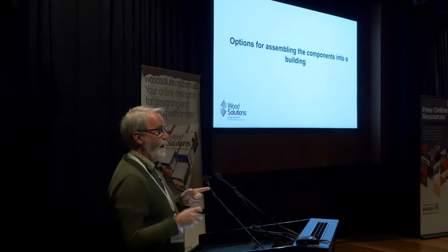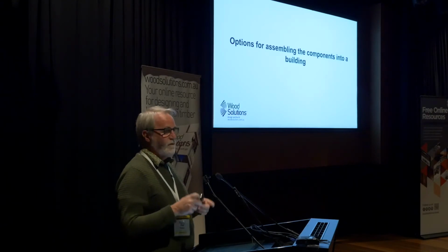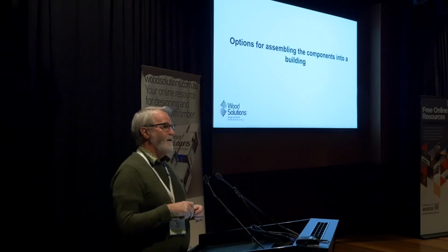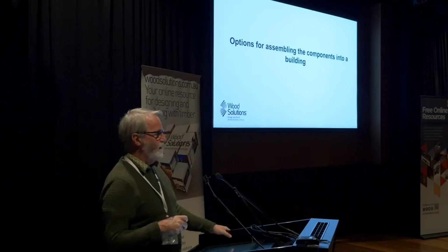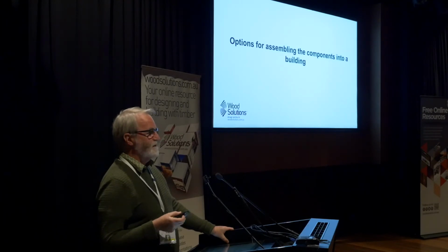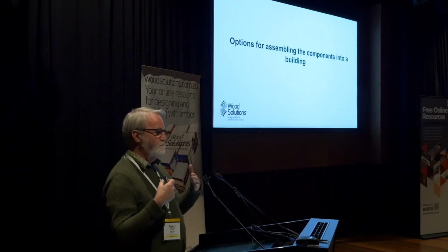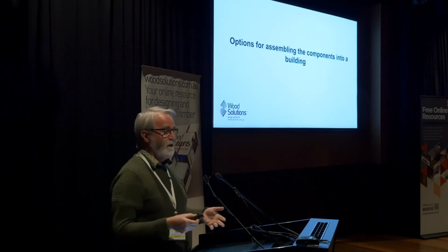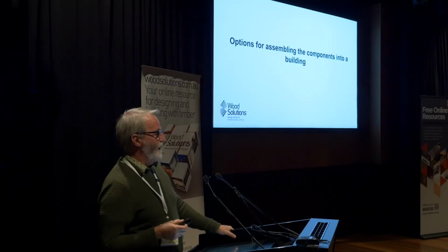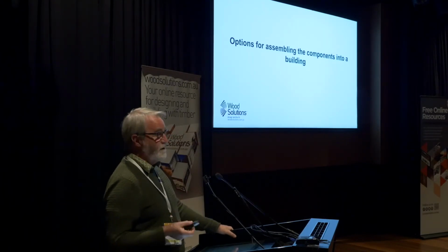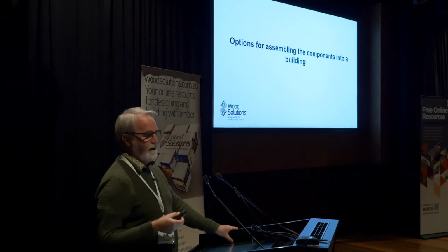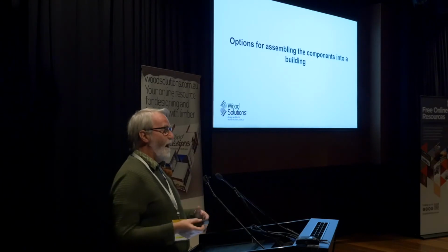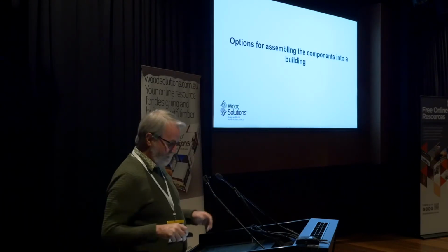We have attempted, wherever possible, to get basic structural characteristics for each of these materials in. So we actually do have, from one or two of the LVL producers, some of their basic performance characteristics of their products, and we've sort of amalgamated them together to give you guidance. Some of the products, though, are almost impossible, so it's almost impossible to get what bending and stiffness is for some of the OSB products that are brought in Australia. So we obviously haven't included them, but we would have liked to.